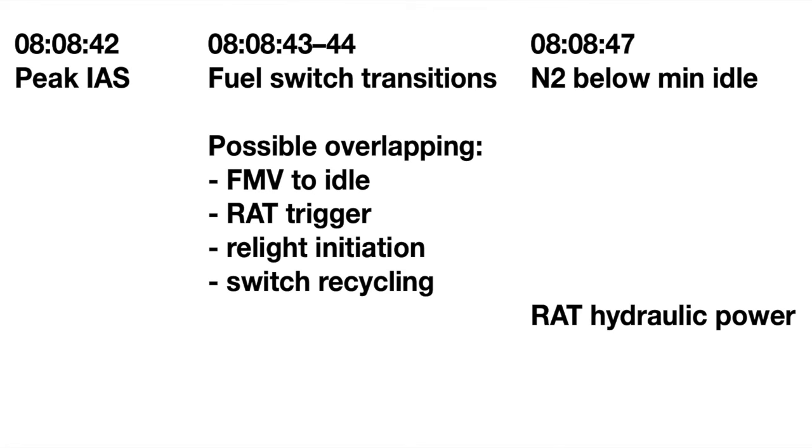Within a very short interval after liftoff, multiple events appear to have occurred in close succession or partial overlap: a possible FADEC data link effect with the fuel metering valve movement toward idle, the fuel switch recycling, engine shutdown, RAT auto deployment logic, and the initiation of relight logic. On the presently available record, the precise internal order of those events cannot be established.